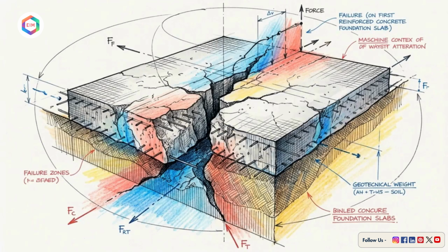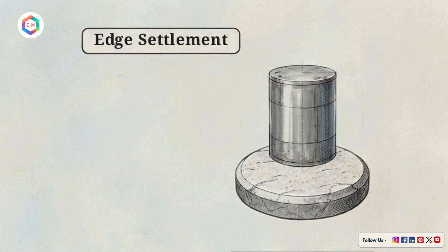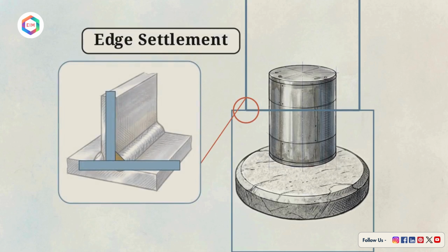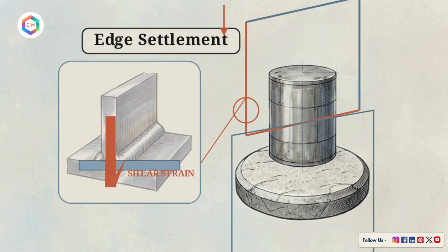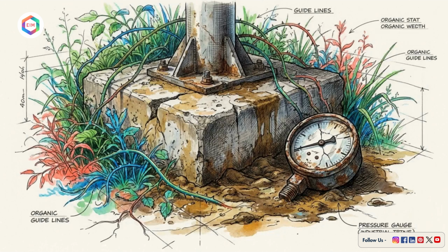Even with sound steel, the ground beneath the tank can fail. Edge settlement is the most damaging geotechnical failure. As local foundation pockets sink, they drag the tank wall down, localizing extreme shear strain directly onto the critical shell-to-bottom weld. Relying on passive safety features or uninspected subgrades without active, skeptical verification is indistinguishable from guesswork.